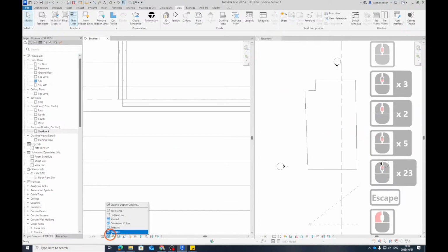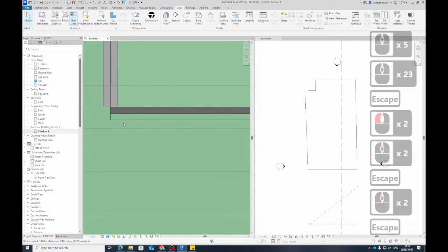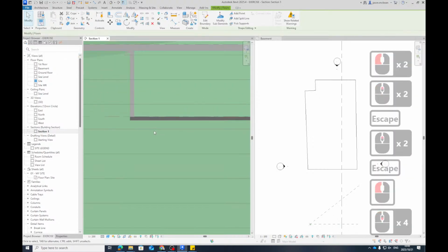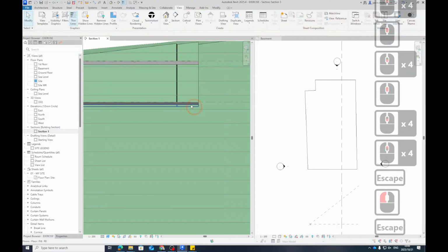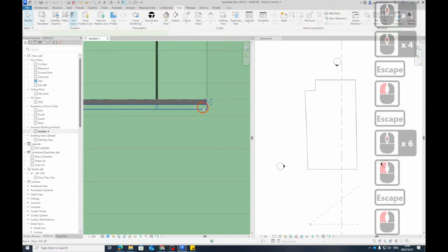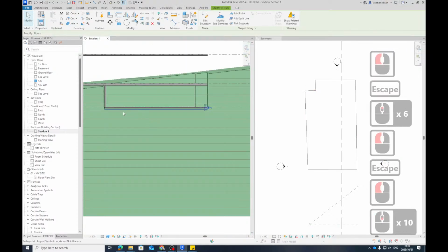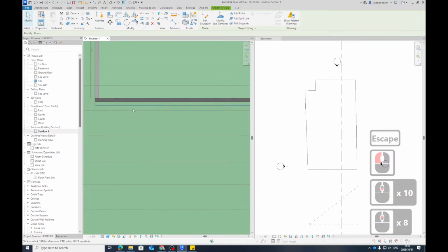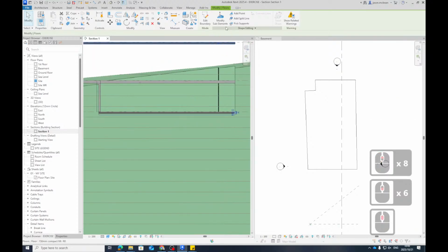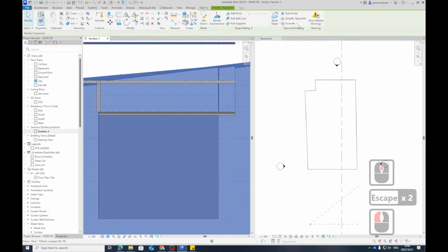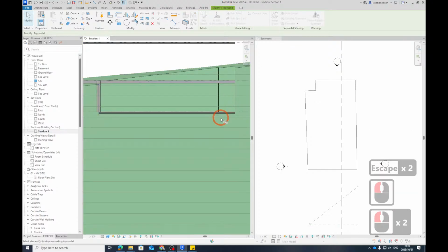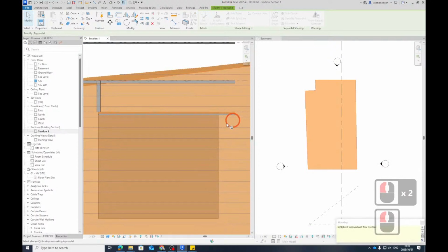Now, if I switch on shaded, see, this now will become my excavating element, not my floor slab. Now I usually make this bigger. I'll start drawing some walls, and I'll explain why I make it bigger. So I'm going to select my topography and say Excavate, Remove Excavation. So I'm going to remove it from that one.